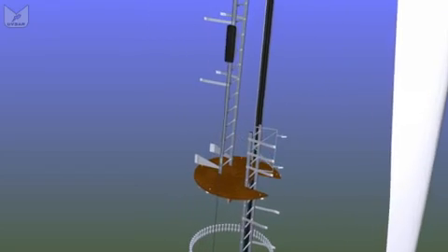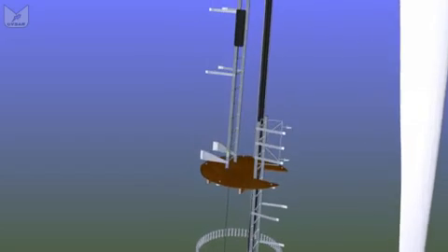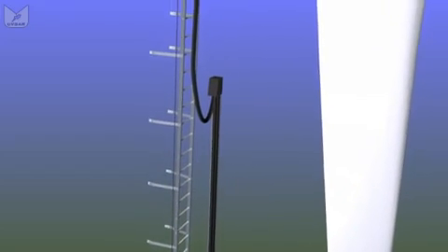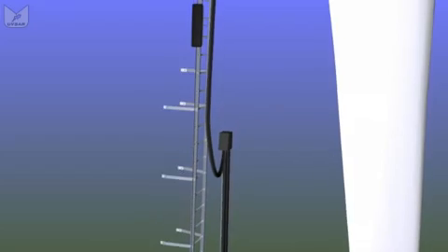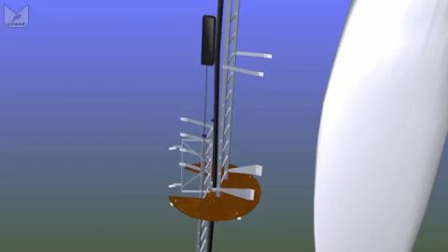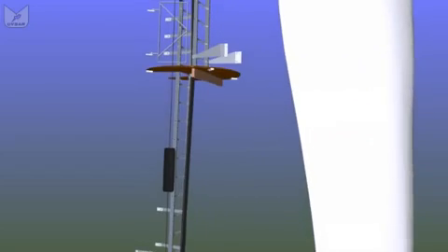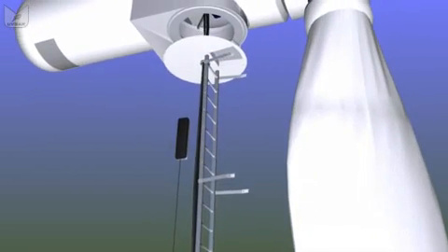But eventually the main cables stop being attached to the wall and they hang freely in the center of the tower, so they can twist as the nacelle rotates to face the wind. If they twist too many times, the nacelle will spin itself around to remove the twists. But as we move up, now the cable goes through a hole in the center of each platform, and at the top of the tower we have a steel platform with a sealed trapdoor, which we call the yaw platform.